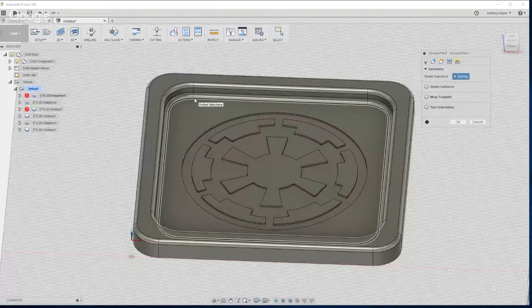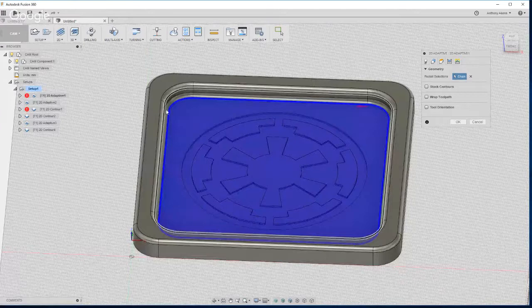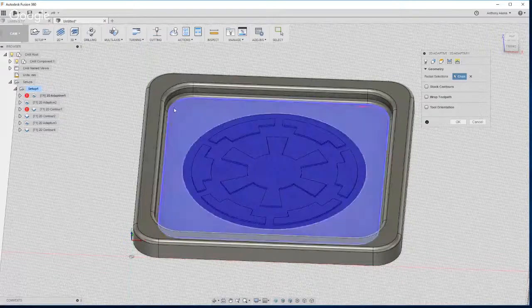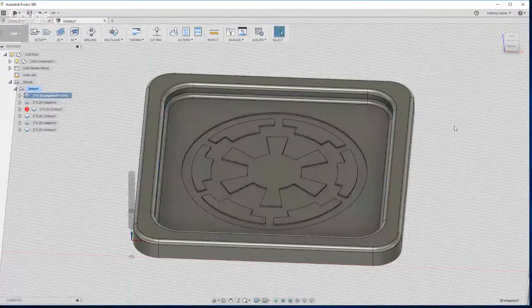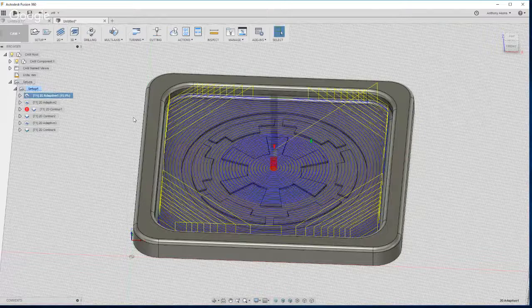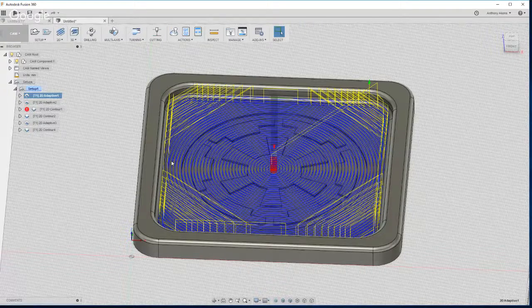I'm going to click two places here on the geometry. I'm going to click the bottom edge of that rounded corner. I'm going to click the top edge of that rounded corner and say OK. And that kind of separates that pocket into 2 points and leaves that little step of a corner only. So the adaptive should be much quicker to clear the bulk of that, and I can use the ball cutter just for that little corner.